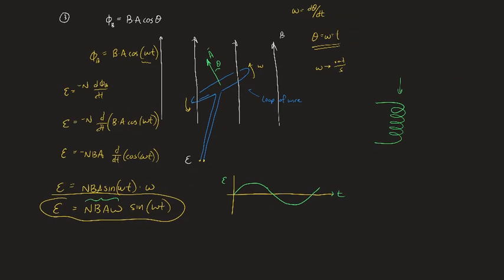All you have to do is apply another set of coils near this one, and you could have the two coils interact. And the EMFs that are generated by one or generated by the other would be related to the ratio of the number of loops. I passed this around, remember? Did you notice that when you took it apart, there was one that had a very high loop density and one that had a very low loop density? Using a system like this, and we'll do this in class, you can step up or step down your voltage without losing any electricity or any energy. You're exchanging voltage for something else.